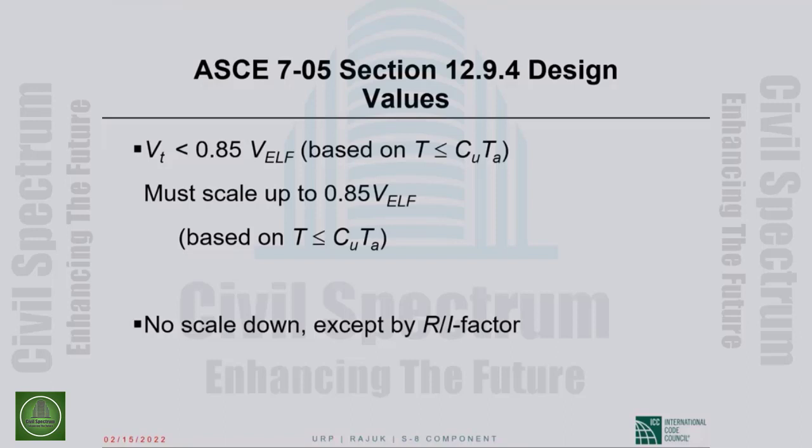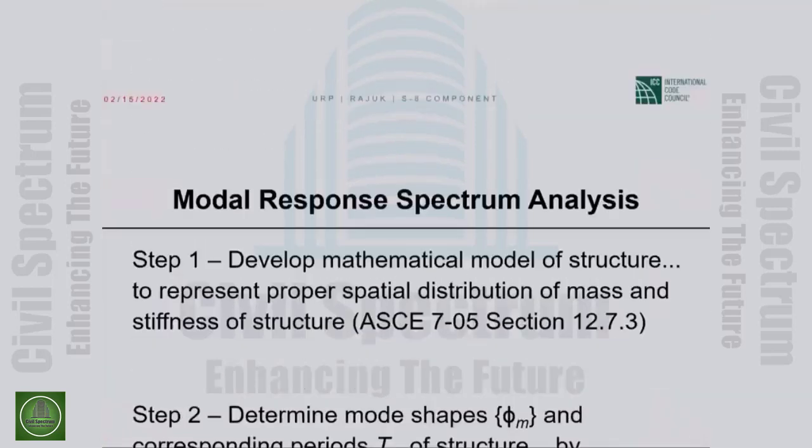We do not do elastic design. We do not design our structure for elastic response to the design earthquake when we do dynamic analysis. So we will still lower the spectrum by R and amplify it by I. That doesn't go away.